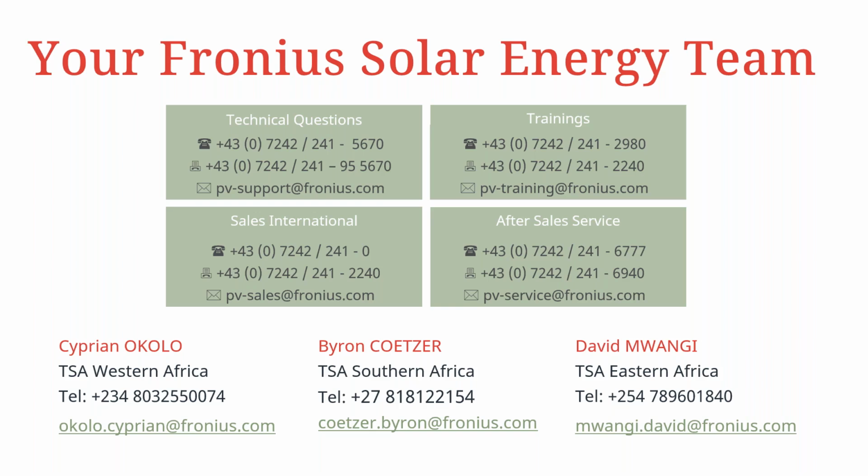What happens is it makes sure that the genset is covering that amount of load, which is referred to by the CTs. After that, the PV is allowed to inject the additional power into the system to compensate, once that 30% load has been covered by the genset itself. Exactly. Great. Thanks a lot.